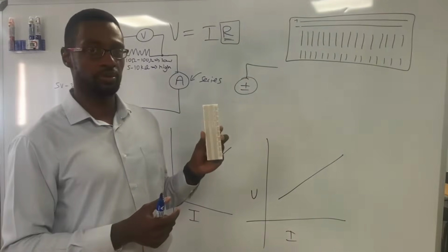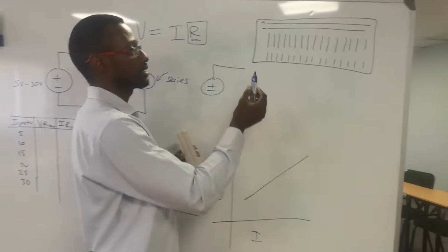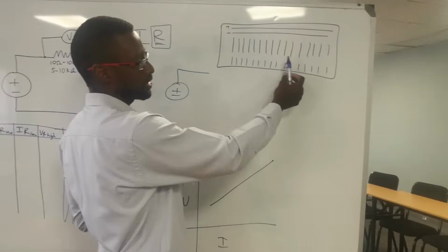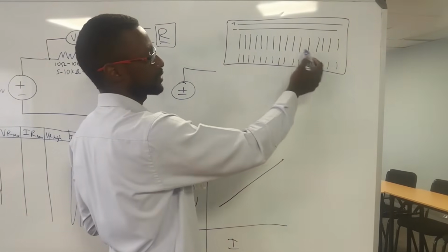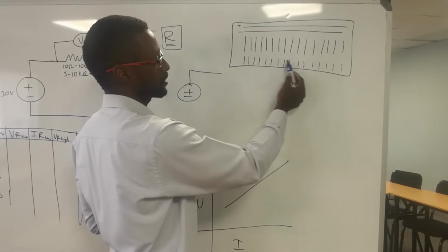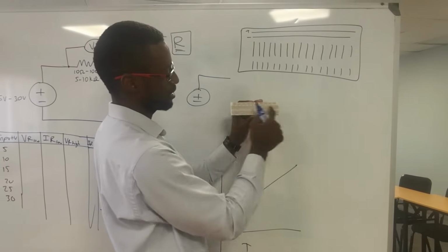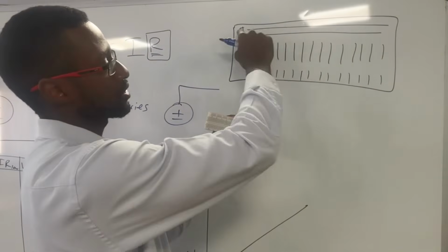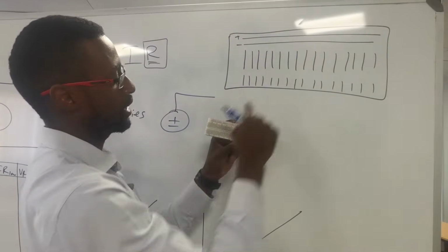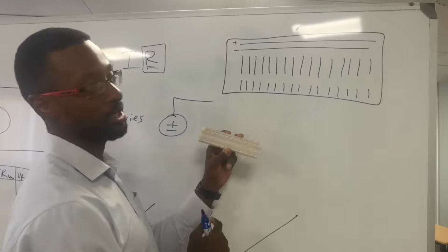All right, so your breadboard, you'll remember that the internal configuration of the breadboard, as we had discussed, has vertical short circuits. Vertical short circuits there, that's what you see here. It's vertical short circuits, and then two horizontal lines going, the positive and the negative there.